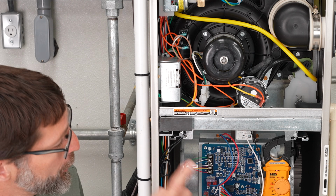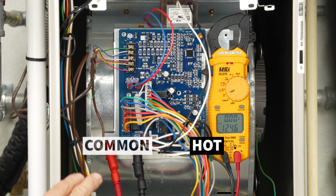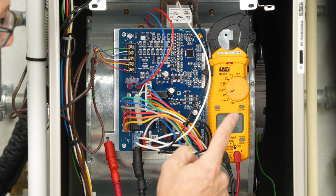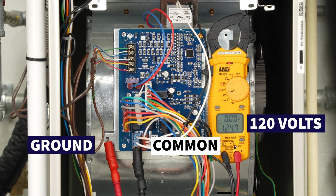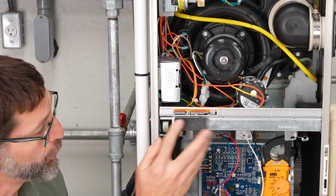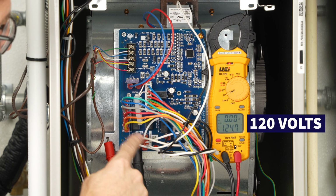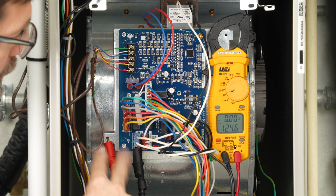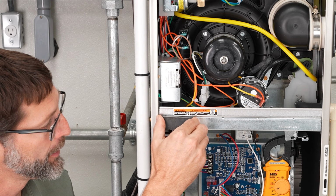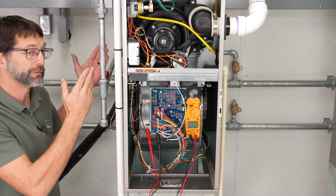With the cover off and our door switch closed, we have a rapid flashing light indicating that our electrical polarity between the black hot wire and the white common wire are reversed. In fact, we're actually measuring 120 volts between our common and our ground, and we should be reading 0 volts. And even if we were to open up this door switch, we're still measuring voltage down here because we somehow have power onto this common wire, and that's no good. So this should be reading 0 volts right now, and with the power off to the furnace, we would need to identify where the problem is.